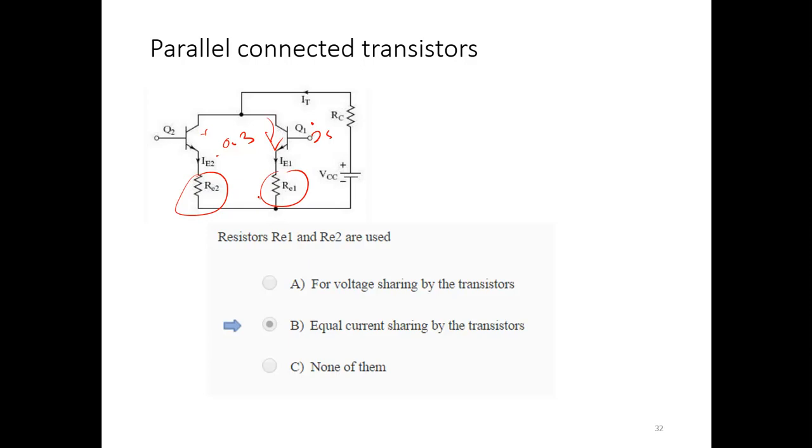That's why you need those resistances for current sharing, the equal sharing of the current. But you're not talking about a very large resistance, very small resistance, ohms or milliohms, so that it matches. Okay, but if you give it too much resistance, then it will limit the current there. You give this for matching, just for the imbalances you have in the internal characteristics.